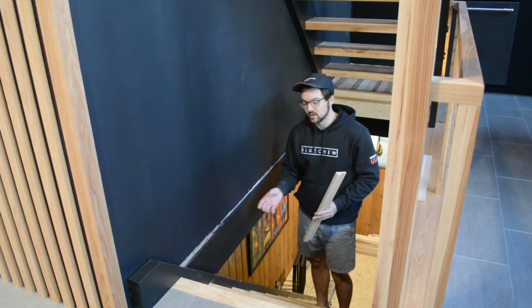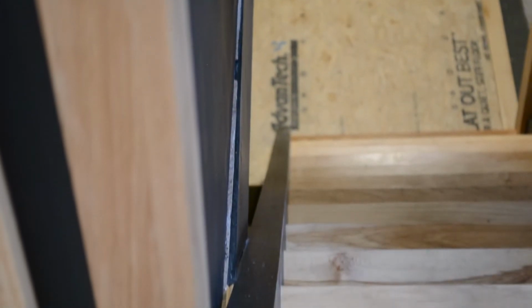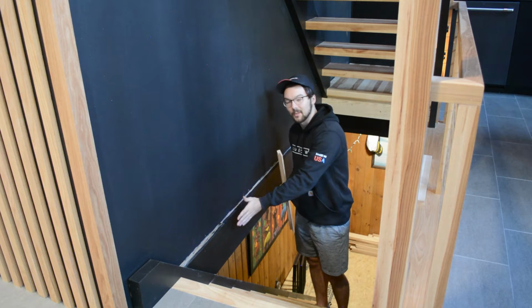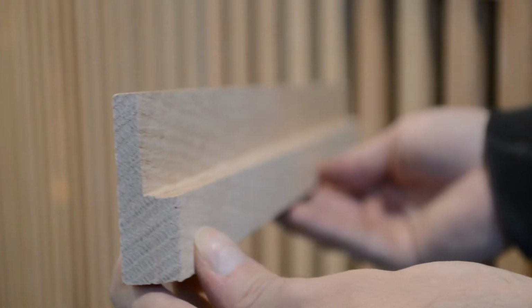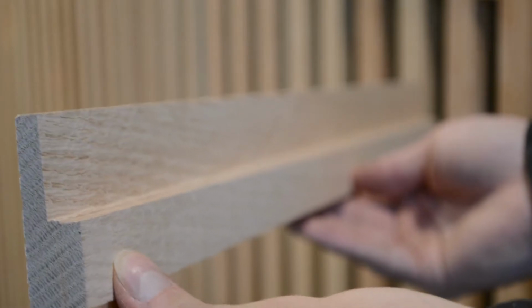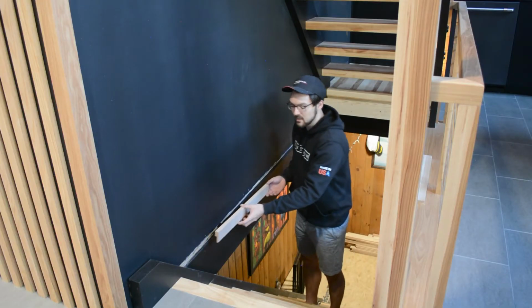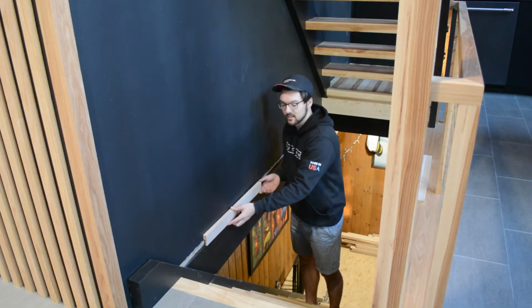So now before we install that piece, there's a little bit of a ledge here just from the old subfloor and the new rim joist of the staircase. It doesn't line up perfectly flush with this MDF, and so I cut a test piece that has basically a cutout so that I can fit the piece around this and make everything nice and flush.